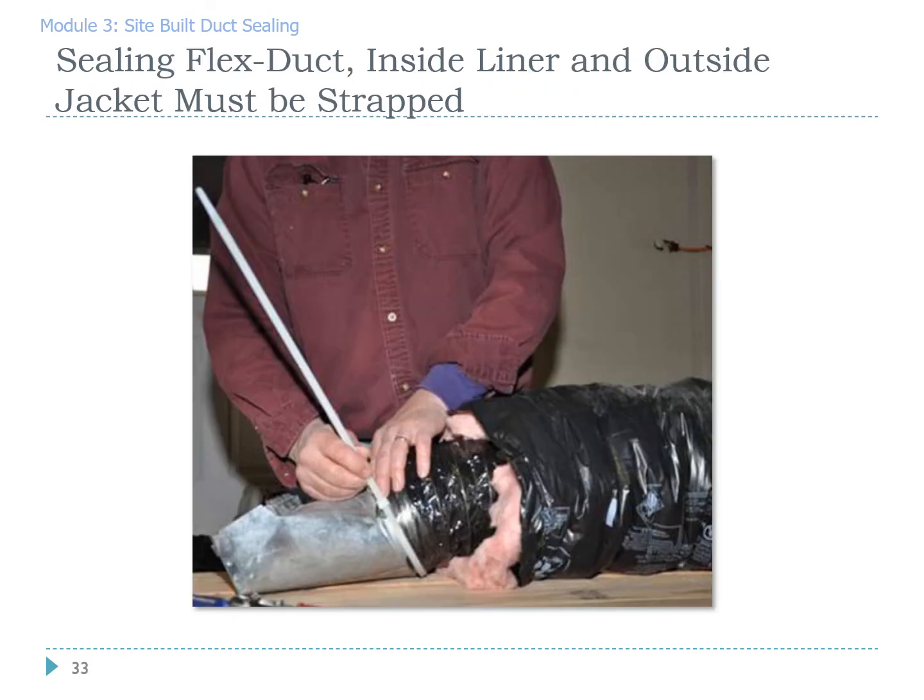When attaching flex duct to sheet metal, it is critical that you use a tension tie tightened with a tensioner on the inside and outside liner. Please note that this program does not require mastic underneath the inner liner and the sheet metal.